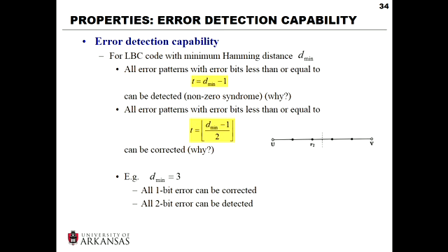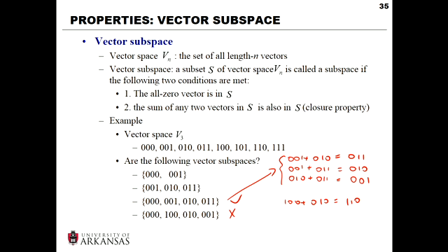All right? So the basic idea here is quite obvious. The design of a channel code is just to maximize the minimum Hamming distance, okay? But that's not an easy task, obviously. So one of the commonly used theories for the design of channel codes is algebra, okay? And the foundation of algebra is the vector space, because all the sequences, put together, form a space, right?